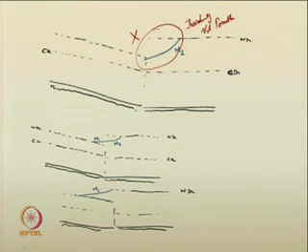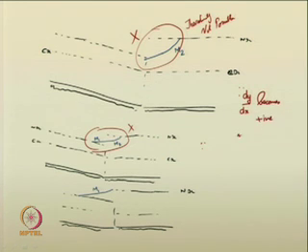Again in this case, the M1 is theoretically possible, but as soon as from this center line to here in channel 2, the curve is M2, it is in zone 2 and it is positive. So, that is also theoretically not possible. So, this is also theoretically not possible, because in both the cases dy by dx becomes positive in zone 2.